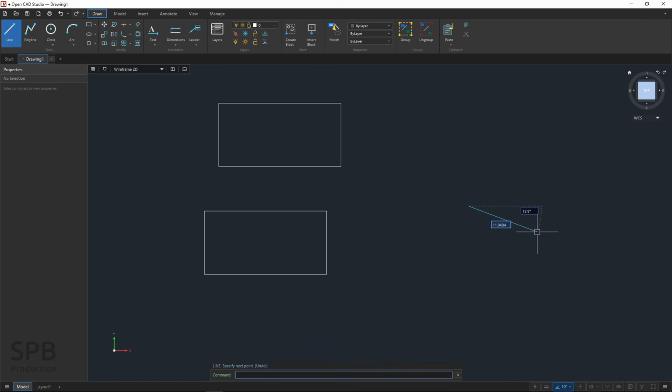So now it would be easy for me to create a square that is rotated 30 degrees because I could draft it like this with the sides of 10 and snapping to these angles. So these are the increment angle settings. You can see you have got these options here.